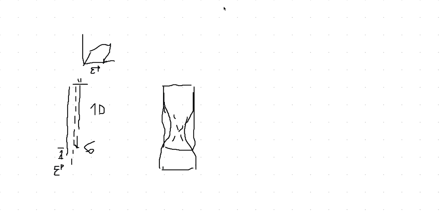So for this particular case, I have my sigma, which is a stress tensor, and it has only one stress component, which is here. If I took my x-axis again in this direction, this is my sigma 1 that I simply call sigma, and all the other guys are equal to 0. So I won't go writing them. Well, some of them, if you want, okay, there, and then all the way down. So all the other guys are 0.